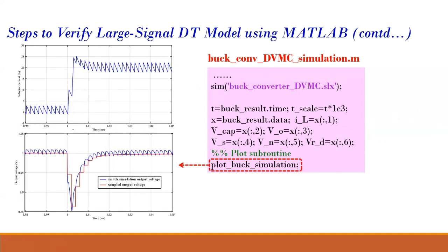So these are the plotted results. This is how my inductor current is changing from one condition to another condition. That is, there's been a load step up. The load requirement has been increased. Whenever there is a load step up, you'll observe that the output voltage falls. Because of the closed loop which is working, the digital voltage mode control, there is a dip in the output voltage, but finally it is getting regulated back to its steady state regulated requirement of 1 volt.